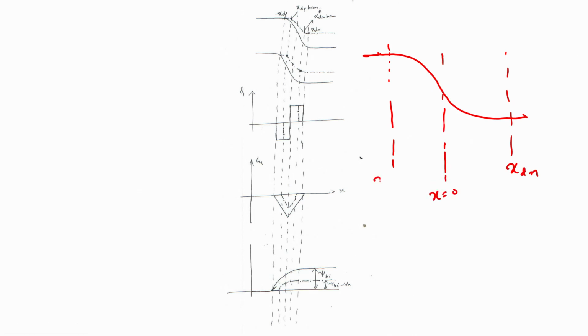So, to give you an intuitive feel again, just to summarize what non-equilibrium does, let me draw this much more clearly. Let us say that was my equilibrium case, that is the band bending in equilibrium. That was the value of xdn. Let us say my x equal to 0 is somewhere here, and that is my x equal to minus xdp, and that was the built-in potential right there. So this is all at equilibrium.